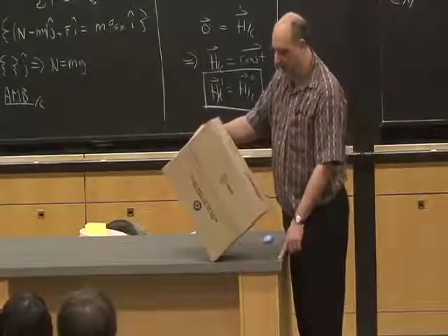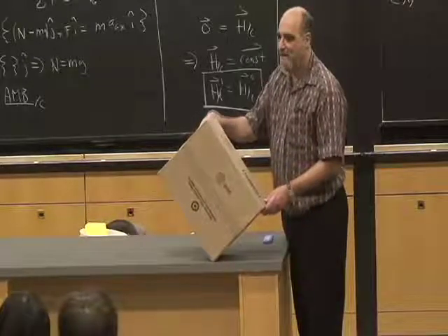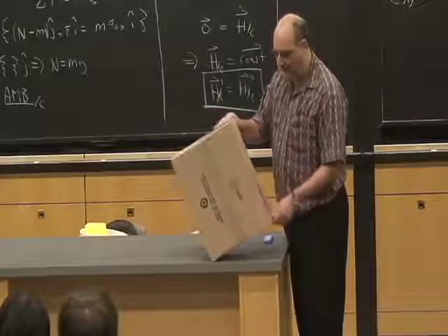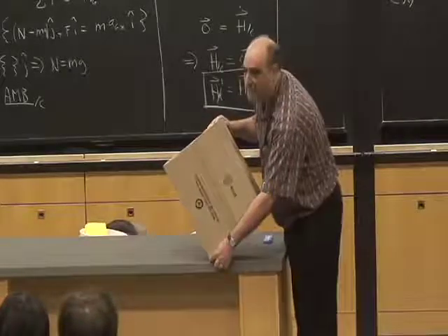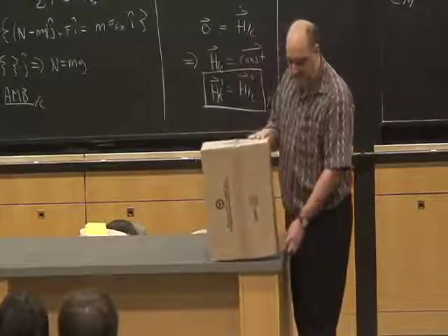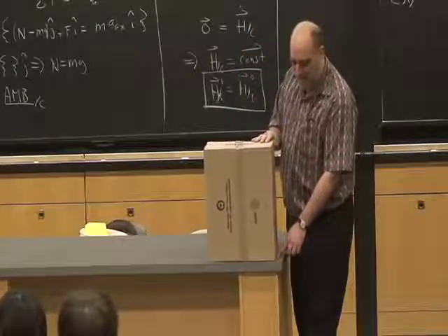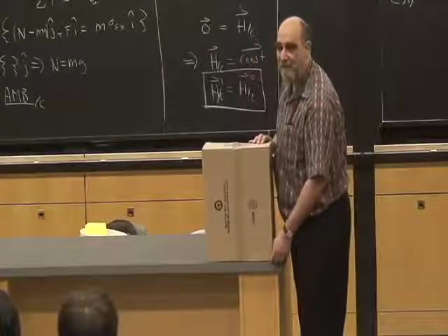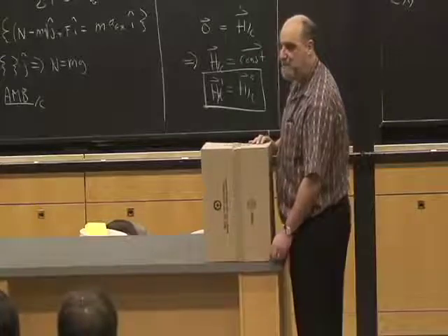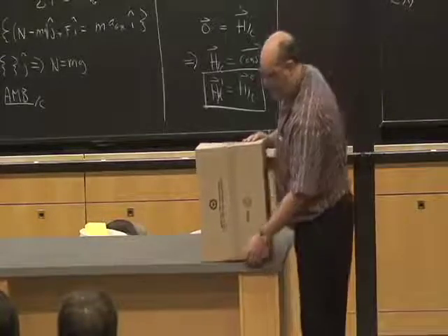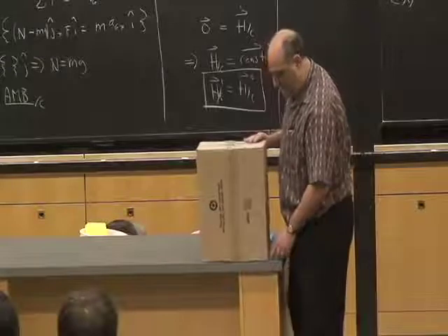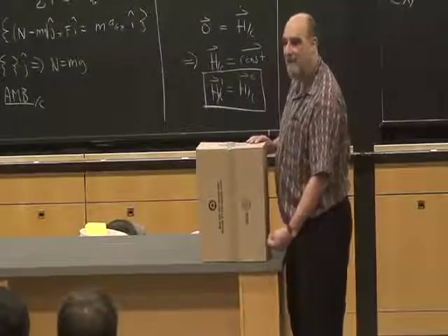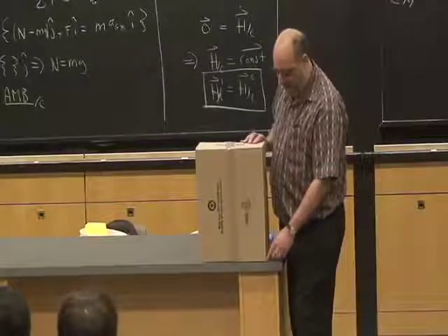So what we're going to do is we're going to take this process and break it down into steps, so to speak. Which is, first, this thing falls, hinged about this point, and let's assume it doesn't slip here, and it conserves energy until it gets to here. Then, let's assume that when this hits, there's no force all along this length, and all the force is concentrated in this corner. That's a big assumption, and it has a huge effect on the answer, but it turns out, at least for this particular box, that seems reasonable. So there's a big force here, and it's a collisional force. We can model it as an impulse. We can just look at the net force with respect to time.